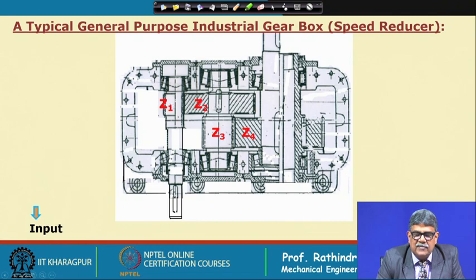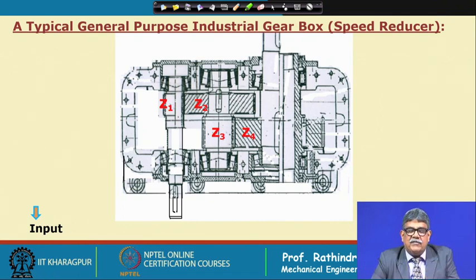If we consider their base circles, we can imagine a cross belt drive, so definitely this will have reduction here, that means there will be reduction in speed and increase in torque, and the torque will be further increased by this one.